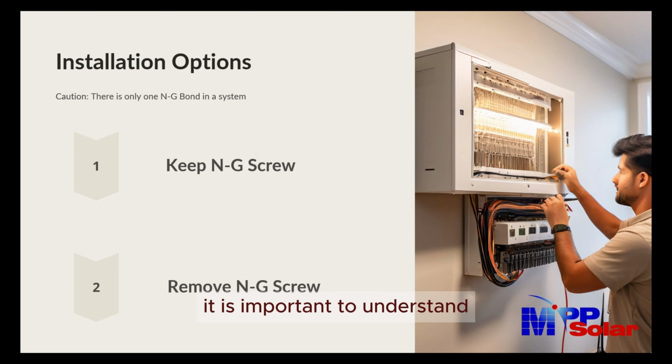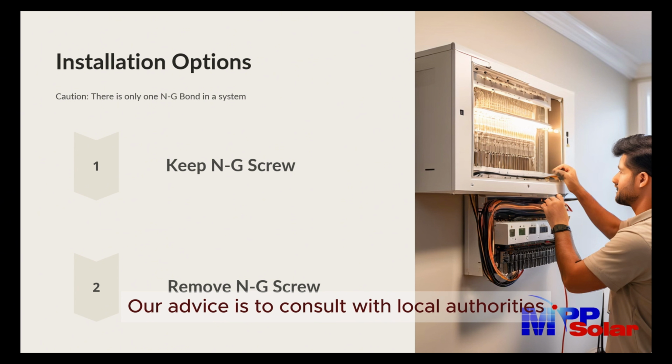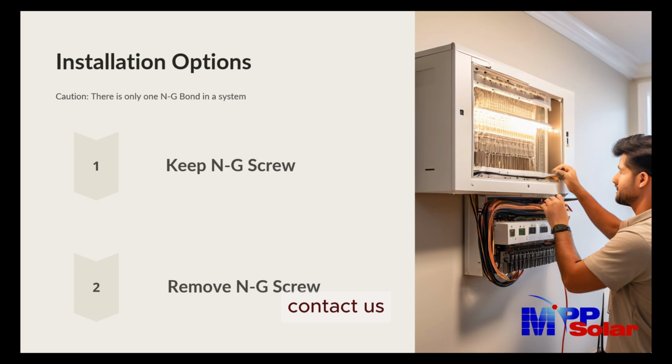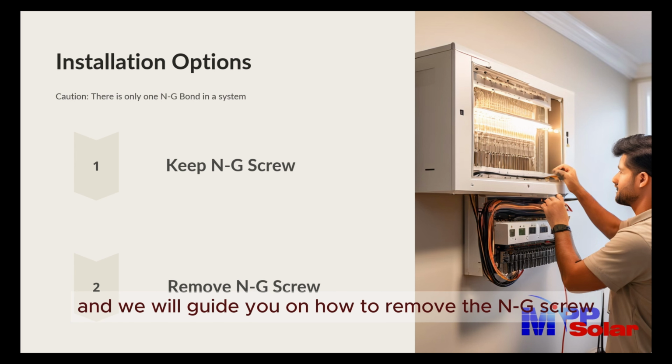It is important to understand neither option is right or wrong, as these are just different practices. Our advice is to consult with local authorities or experts on the best way to handle this. If you wish to NG bond at the output panel, contact us and we will guide you on how to remove the NG screw on your inverter.